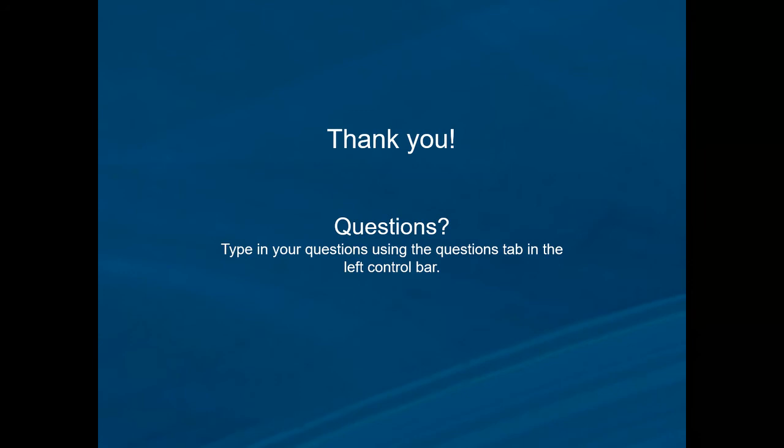Plus or minus 5 is absolutely achievable with electric resistive units that use very clean water, RO or DI water, and use an SSR. Then we've seen plus or minus 1% all day very easily. So again, some of those options are standard on some products and optional on others. So make sure you work with your reps or with us to make sure we're getting the right equipment in there.